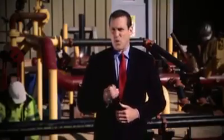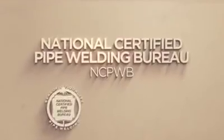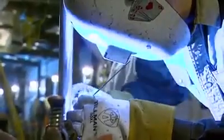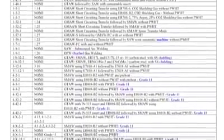To ensure the contractor has the required procedures in place for critical activities such as welding and brazing, the engineer should have the contractor submit the procedures they plan to use and personnel qualification records for review and approval before welding or brazing starts. Contractors who are members of the National Certified Pipe Welding Bureau, NCPWB, a subsidiary of the Mechanical Contractors Association of America, not only have welding procedures that are fully compliant with the B31 codes, but their welders and supervisors have been trained to follow those procedures. NCPWB has over 100 welding and brazing procedure specifications that can be used by all members. This has the benefit that regardless of which NCPWB contractor is awarded the work, the welders and brazers follow the same procedures that they followed on their previous job.